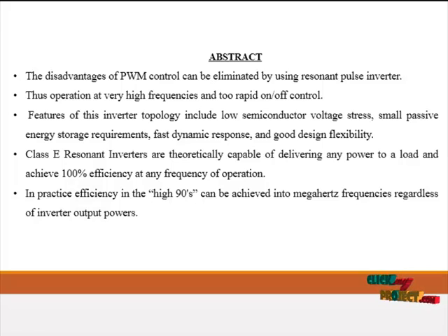Next, we see about the abstract. Resonant switching topologies are the next generation of power conversion circuits when compared to traditional pulse width modulation topologies. Resonance-based supplies are more efficient than their PWM counterparts. This is due to the zero current and/or zero voltage transistor switching that is inherent in resonant supply designs. This feature also provides an additional benefit of eliminating undesirable electromagnetic radiation normally associated with switching supplies.